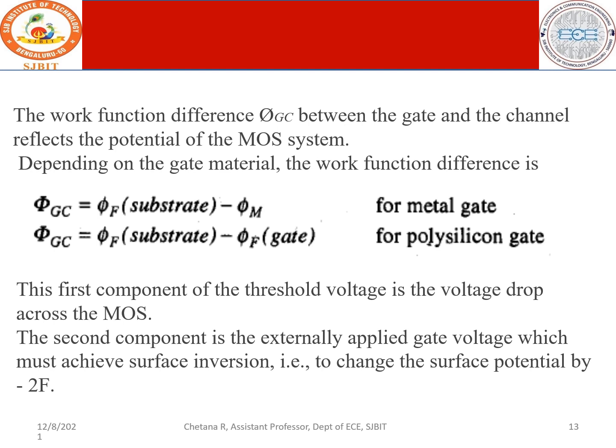So in accumulation, depending on the gate voltage, the charges are just deposited on the surface, and the moment you give the drain voltage along with a slightly greater gate voltage, some kind of inversion occurs. So charges are getting attracted and like charges will get repelled. Unlike charges attract, like charges repel, and that is how the inversion layer is created. So that is the requirement which is called VGS. So please remember, sometime back I told you VGS should be greater than the threshold voltage. If that is the case, it is going to happen.